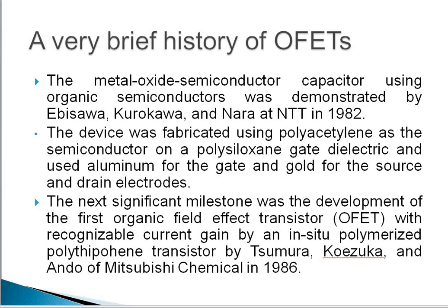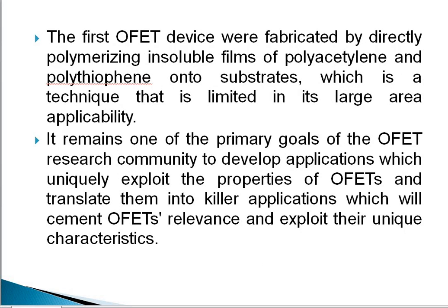The first OFET device was fabricated by directly polymerizing an insoluble film of polyacetylene onto the substrate, which is a technique that is limited in its large area applicability. A soluble form of polyacetylene was developed by engineers and applied to the organic field effect transistor later.